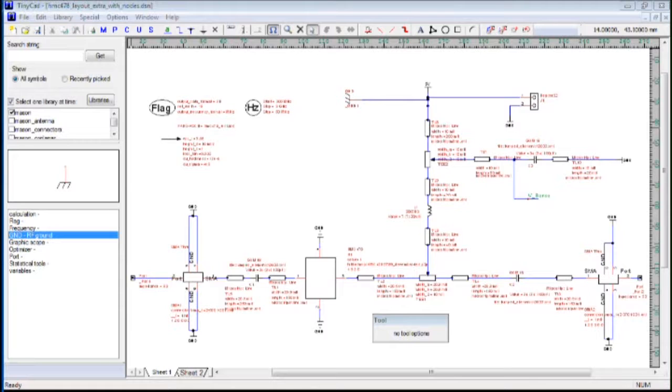This is especially true when you're dealing with vias. Headers, this header is less important. It's just important to be aware when you're trying to get the headers and connectors and devices a certain length away, that the electrical length and the physical length might differ a little bit.